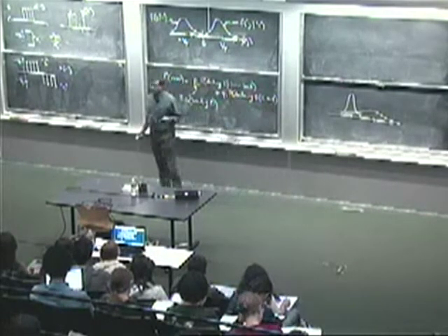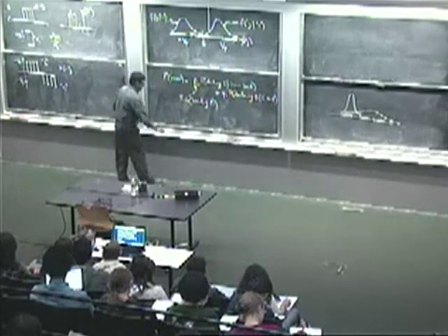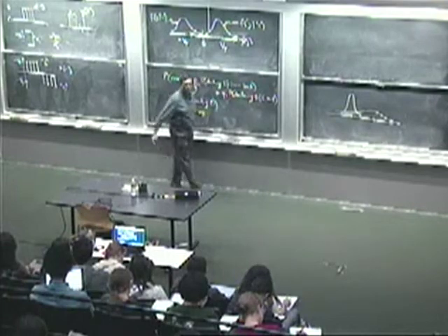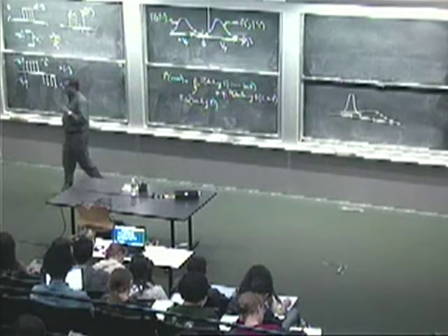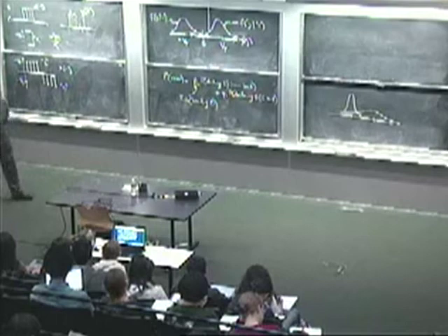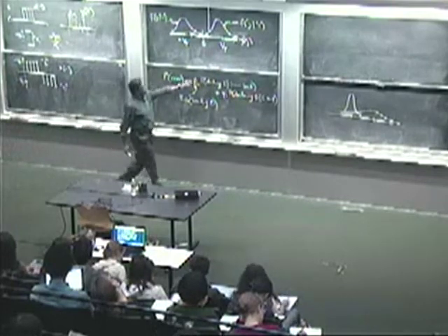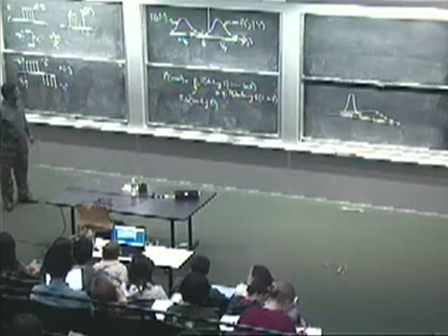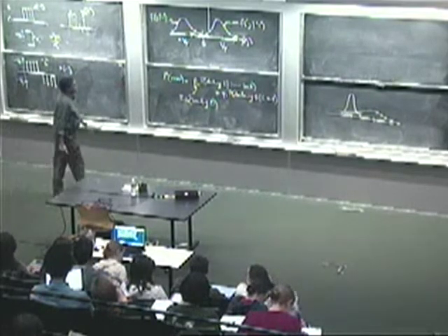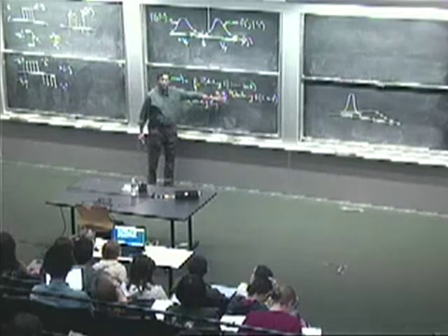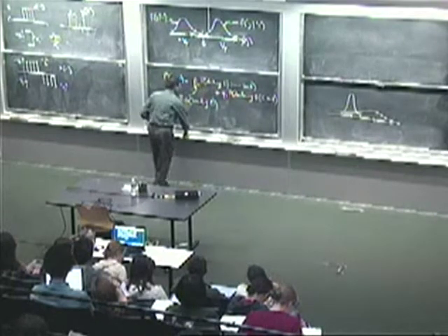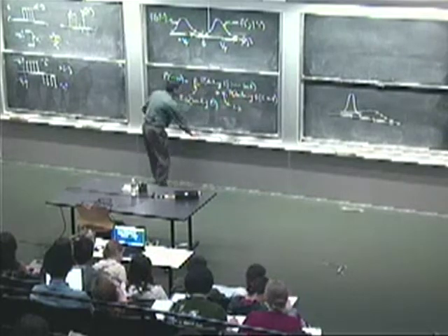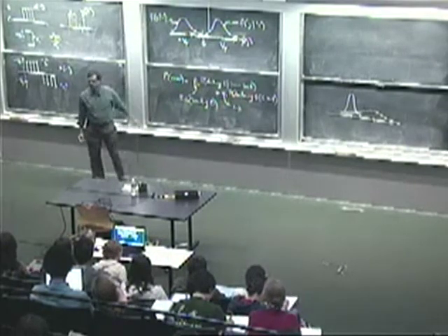So it turns out these are the only two ways you can make an error. And these are mutually exclusive, and so what you're doing is adding the probabilities of the two ways of making an error. You can either have a 0 sent, and then the question is, what's the probability of declaring a 1 if a 0 is sent? And then you have the corresponding term on the other side. If P0 equals P1, in other words, if both of them are 0.5, then you can pull that out.